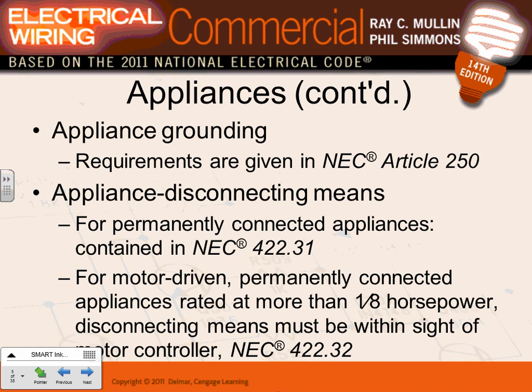There are multiple shapes of disconnect. Guys, here's a disconnect right here. This guy qualifies as a disconnect. The plug can qualify as a disconnect. A snap switch for small appliances is a disconnect. For bigger appliances, you're going to have a NEMA-rated disconnect switch right on the wall where you can lock it and tag it. This is another application for a disconnect. So that's basically what this is telling you.